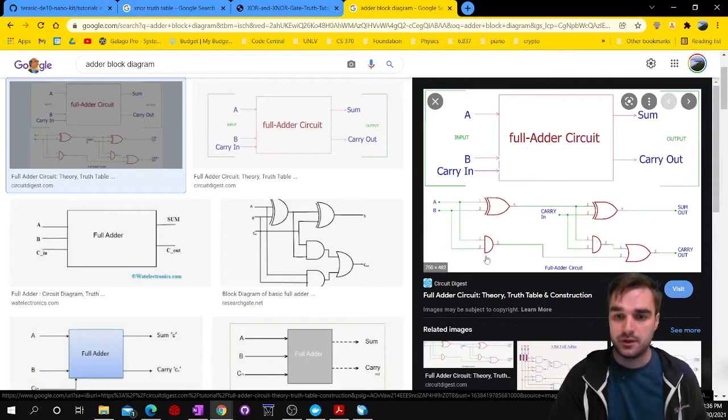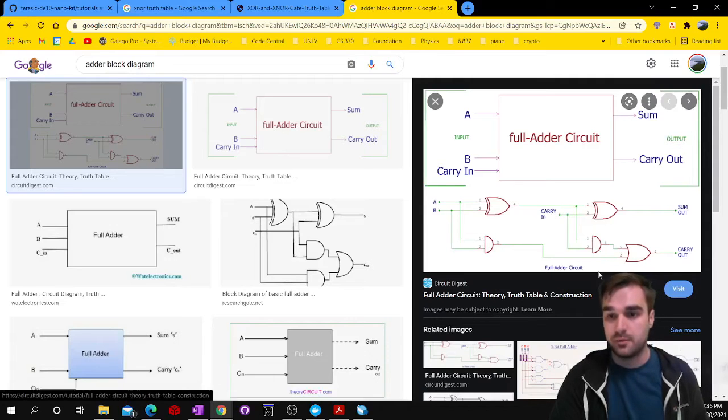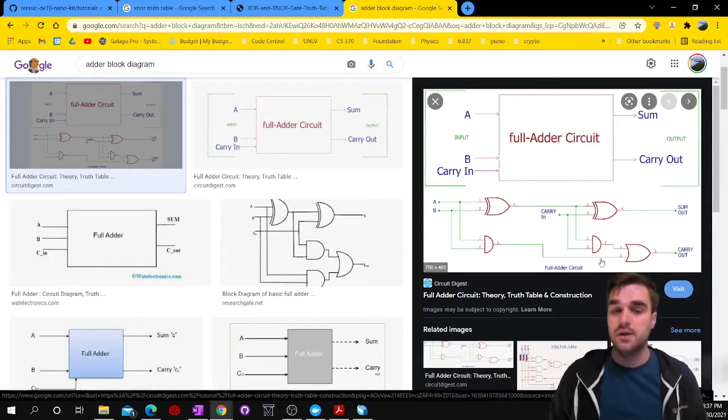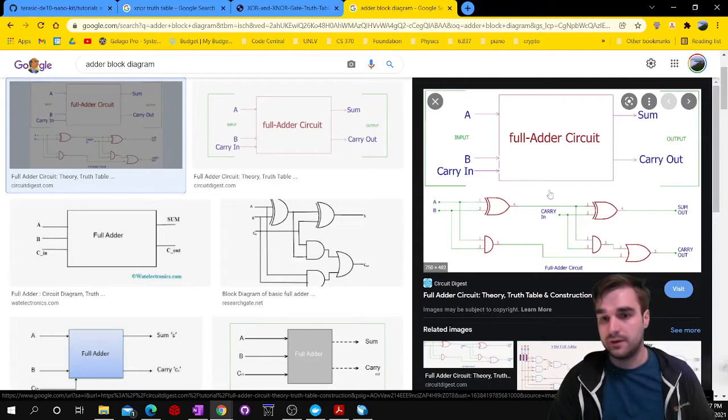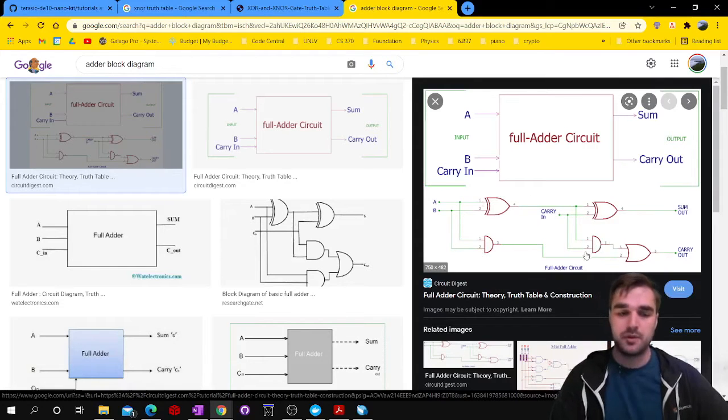This is the logic required to add 2 binary numbers together in a simple adder. And this is definitely a video I'd like to make. I don't know if we'll do it in a block diagram, but this is why it's important to understand what's happening with the block diagrams, because that's ultimately what you're going to be writing in your Verilog code. This is nothing like programming in C. You need to be thinking about these logic gates, and that's why we're starting with the block diagram.